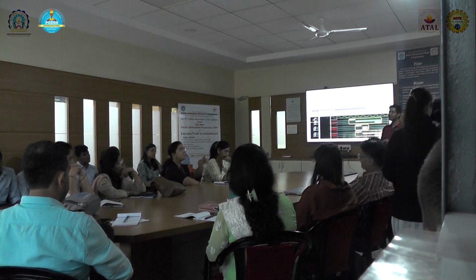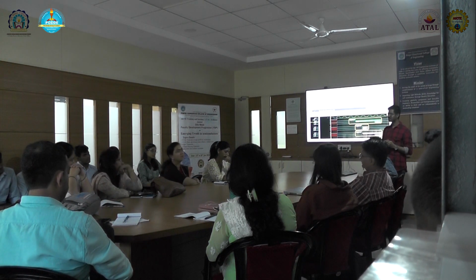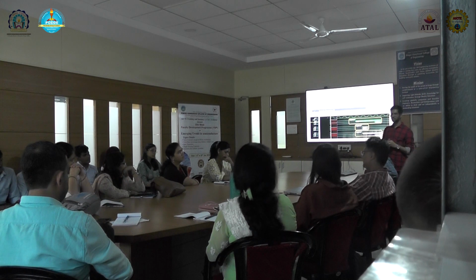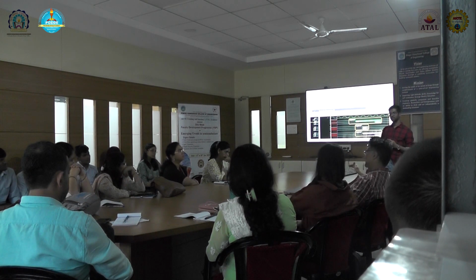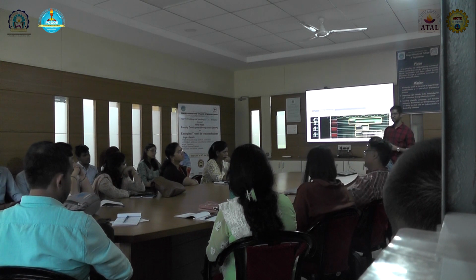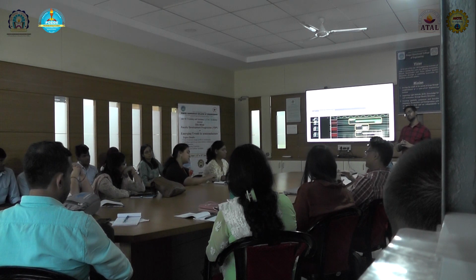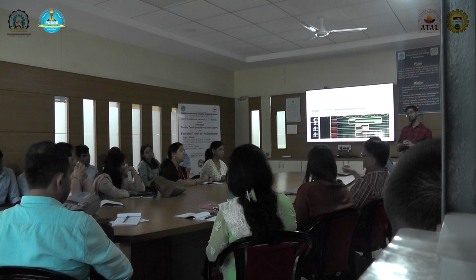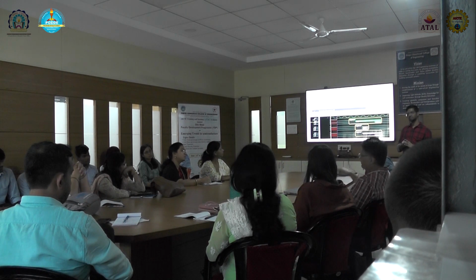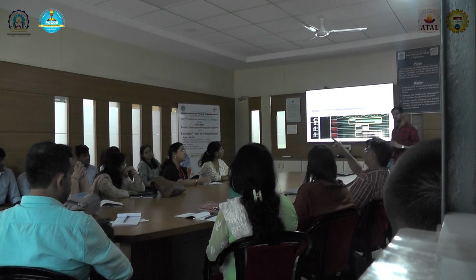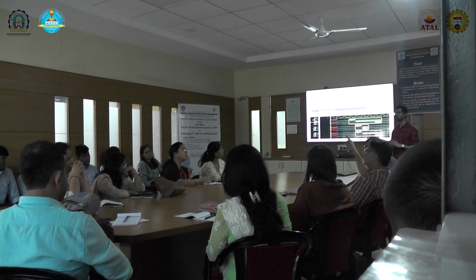So I write this as per the specification, because the rates are matched. Input आया and on the very next block the output is framed. The FIFO never accumulates and therefore it should never overflow. So it is like making a statement first and verifying, and formal will go and verify whether the statement that you wrote is true or not.